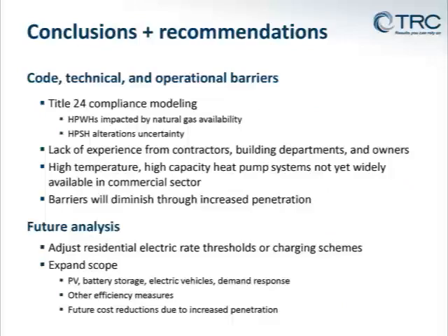On slide 14, I just kind of outlined the code and technical operational barriers. Obviously, Title 24 compliance modeling has some issues. There's a general lack of experience that we found in the Palo Alto region from a lot of different stakeholders, but hopefully that changes soon. In terms of commercial applications, restaurants, for example, high temperature, high capacity heat pump systems are not yet widely available that we found.